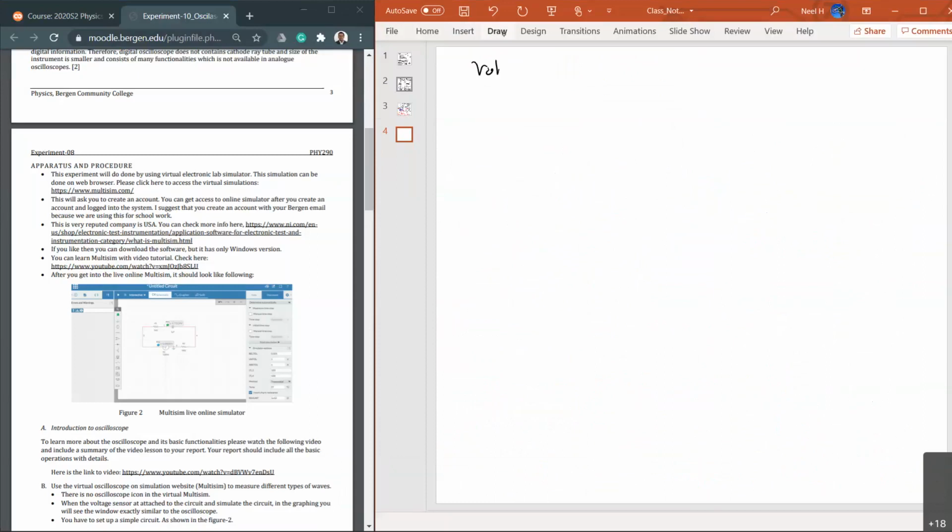And this voltage, usually what we're interested in is VAC type volts. Those are sinusoidal type waves, right? So those are this kind of waves. What we try to investigate is the maximum voltage V0 and the frequency. That means by measuring the time for one complete oscillation, I can find the frequency. So those are the two measurements we try to do.